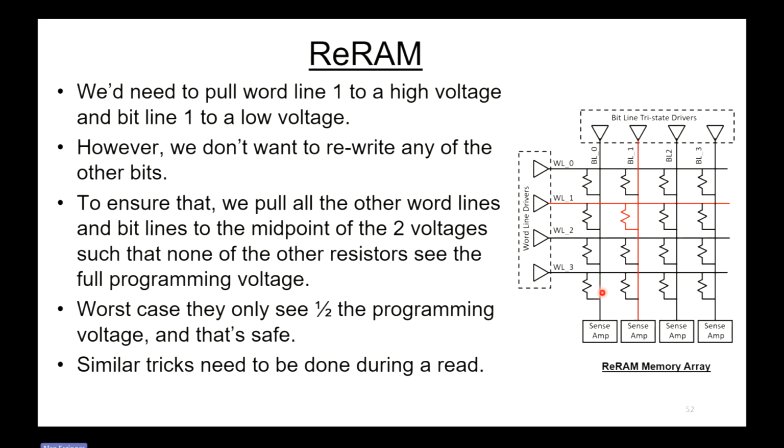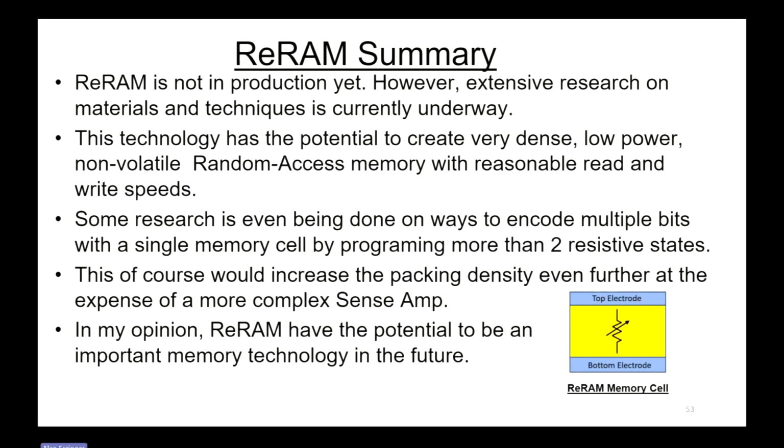Similar tricks have to be done when you're doing a read. I'm not going to get into that, but I just wanted to show you it's kind of tricky because you've got this big array of resistors. Okay, so ReRAM summary. ReRAM is not in production yet. However, extensive research on materials and techniques is currently underway. This technology has the potential to create very dense, low-power, non-volatile random access memories with reasonable read and write speeds.